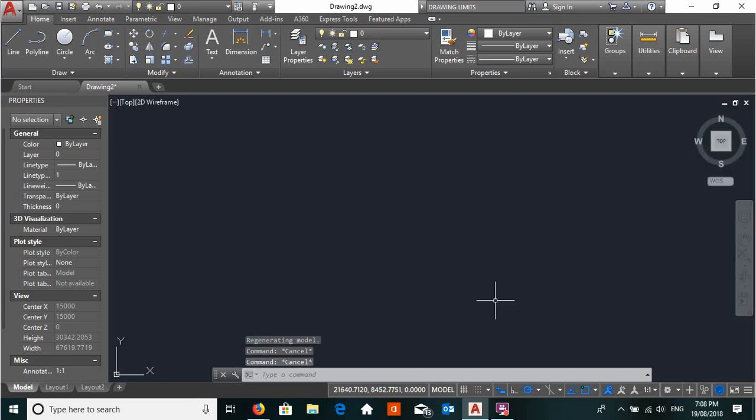Okay, so again, status bar down here, make sure your drawing aids are toggled on. The items in blue are important. So let's switch on ortho because we're going to be drawing walls.